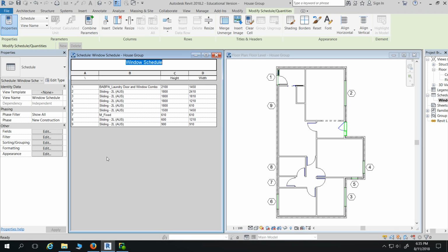I just added 10 at the end. Oh, do you mean like from the... Yeah, just so you've got a brick here and that sort of thing. Nah. We loosely follow it at work, but if the client wants it, they pay for the brick if you cut it. Well, that's why I suppose you deliberately position it so you've got like 590 or 710. Yeah, ideally you'd position it that way, but sometimes it doesn't quite work out and they just pay for the cuts. It's built into the cost.